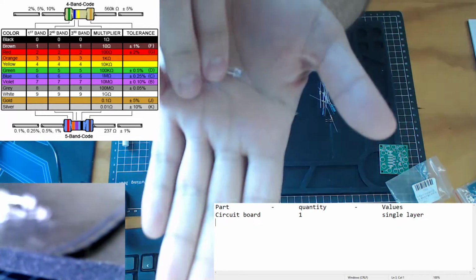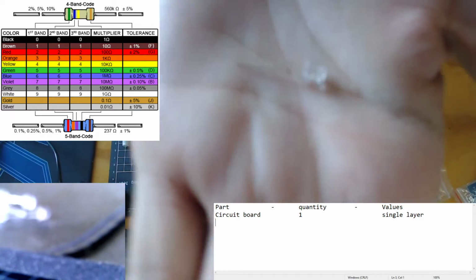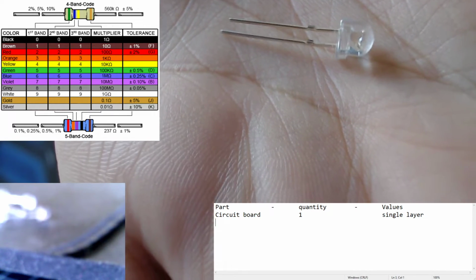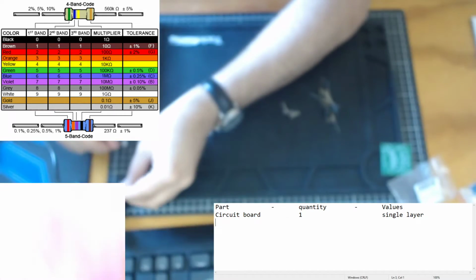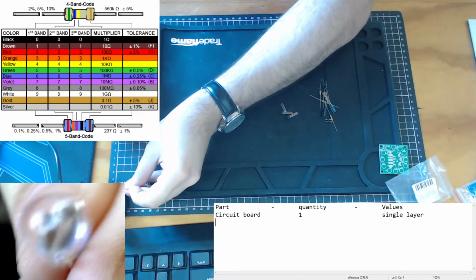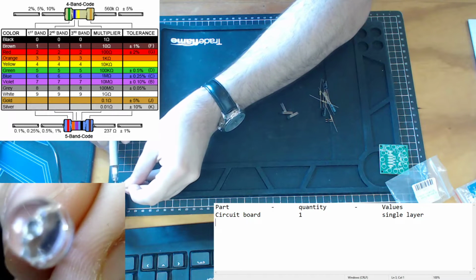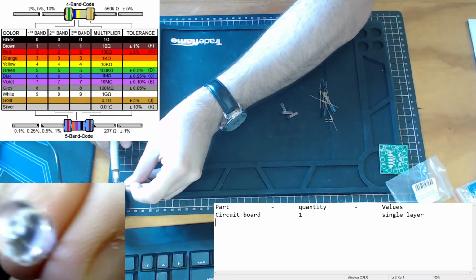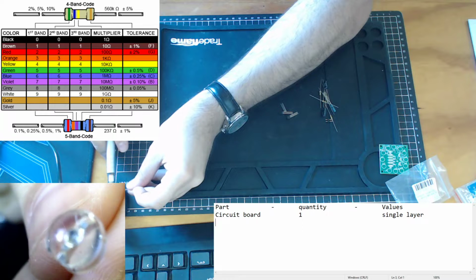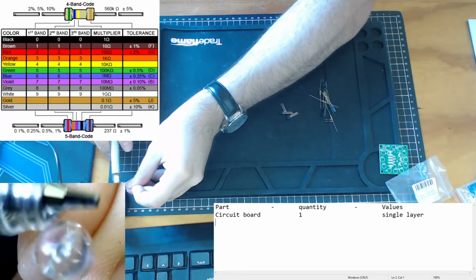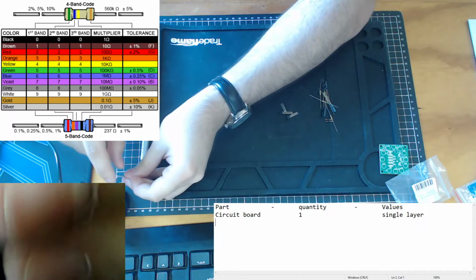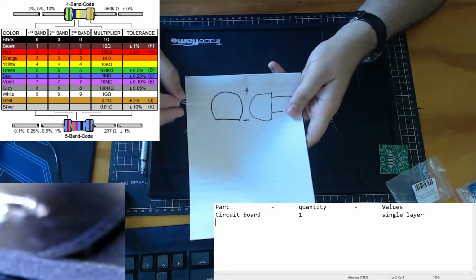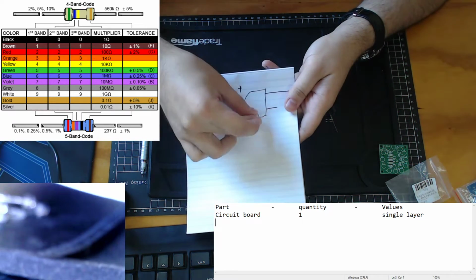As we go up over here, we see that the LED light itself has 2 different leg sizes. Right? And when I look at it on this side camera over here, we see this area of the light over here, where I'm pointing my pen at, see how it's flat? There's some sort of cut over here, how it's flat compared to the other side, which is smooth. So the flat side of the LED light, as you see by my diagram over here, actually relates to the short leg.